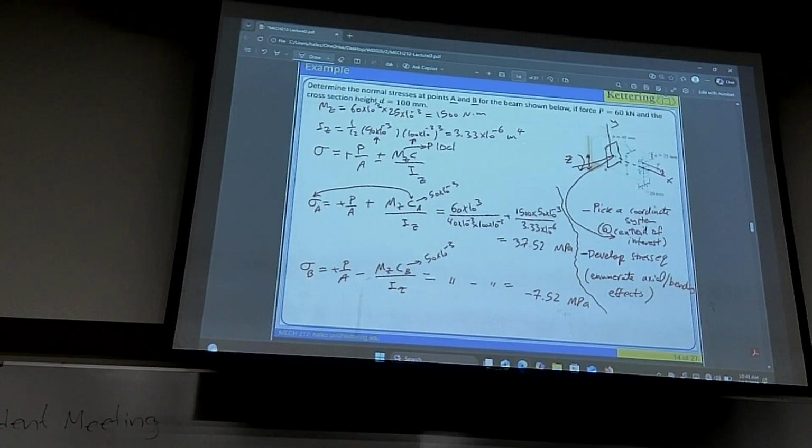All right, so we do all this calculation for a reason, and the reason is: is this system safe? Then we have to know the material property. The textbook did not give anything. So suppose strength in tension is given as 40 megapascal, and suppose sigma u in compression is 5 megapascal. These are just arbitrary numbers for us to be able to comment on that.